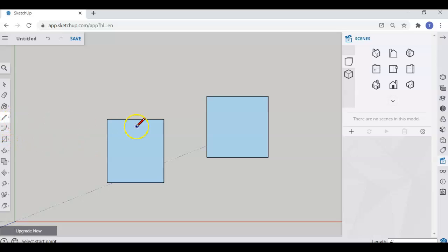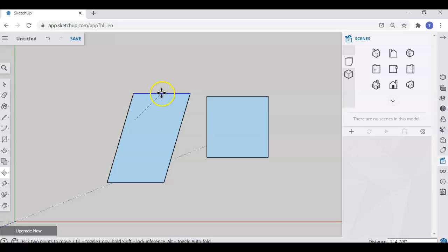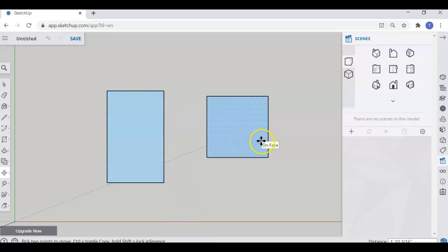I'm going to make my rectangle a little bit longer, because it kind of looks like it could be a square. So I'm going to move this line up a little bit. How I move a line is I go over here to this new tool and click. Notice I can rotate and scale, but right now I just want to move. So click there, and we're going to go over to this line, and I just want to make it look more like a rectangle. So I'm going to go up the green axis. Remember, if you go this way, it's not going to be 90 degrees. So up the green axis and push it. Oh, sorry, not push enter, push the mouse button. Now we've got a rectangle and a square.